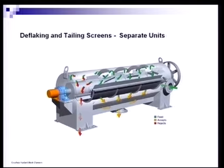Following a secondary coarse screen is often a separate tailing screen. In older mills, these might be vibrating screens, but in more updated versions it is an atmospheric screen, such as this, where it uses half of a screen plate laid down into a frame, into which a rotor is placed, and there is about a 1 millimeter gap between the rotor tip and the screen plate, so that as you turn the rotor, it keeps the screen plate clean.